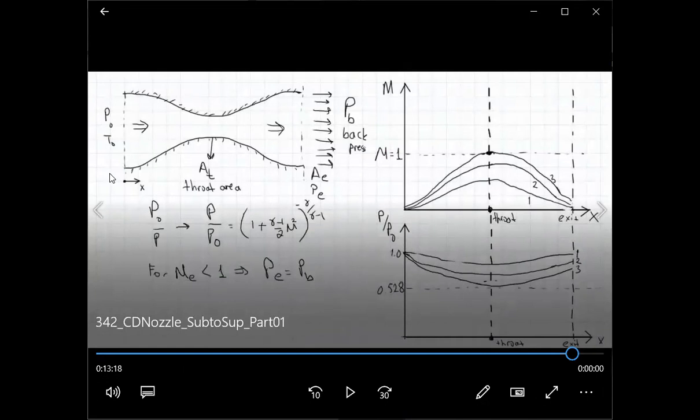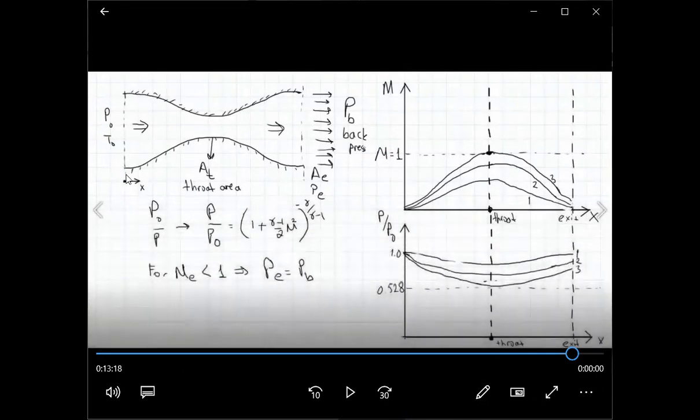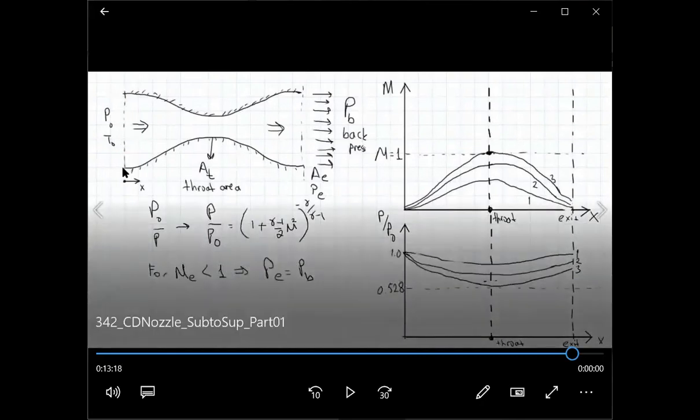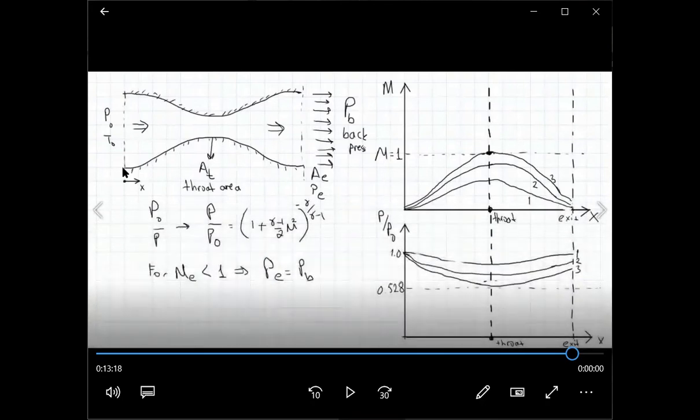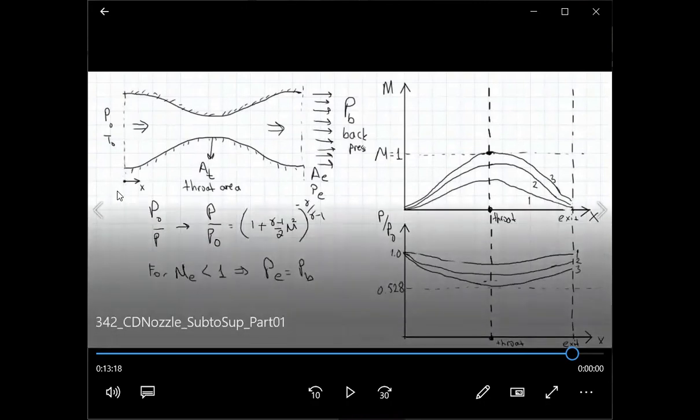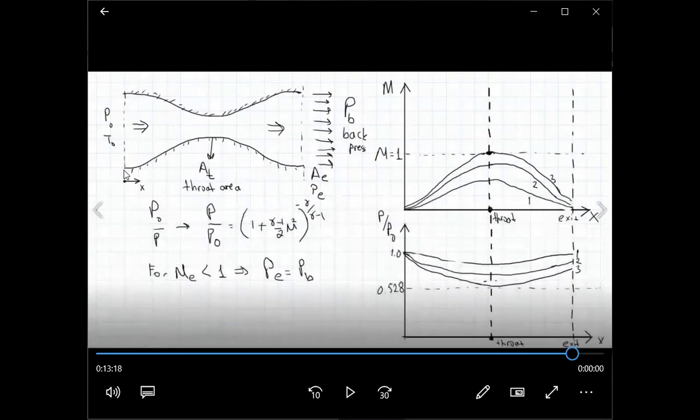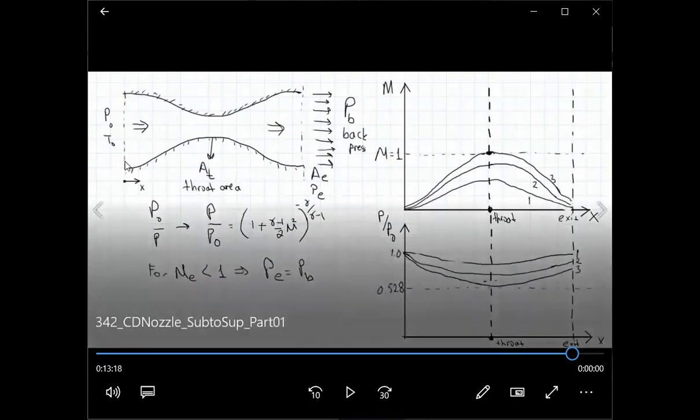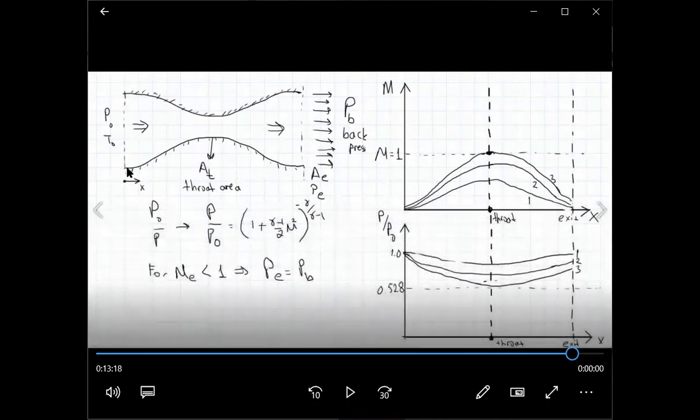It was described partly in the video, but let me explain it a little bit more. At the very left-hand side plane, where we have the inflow condition, we are assuming, as I explained in the video, that this inlet is connected to a very large container, a very large chamber, or it could be the exit of your combustion chamber in your rocket engine just before this nozzle, where Mach numbers are very low, maybe not exactly zero, but very low.